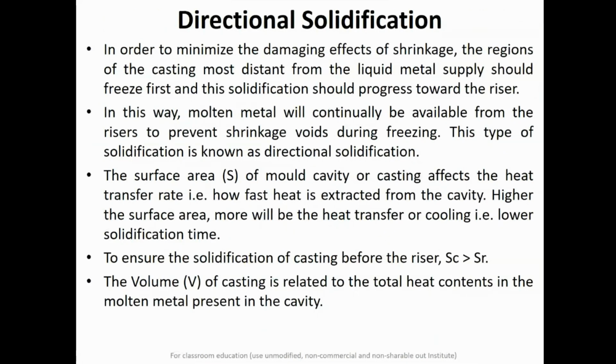Now in casting, we always take care of directional solidification. So what is directional solidification? In casting, we always aim to minimize the different types of damaging defects arising due to the shrinkage of the casting. The region of the casting which is most distant from the liquid metal supply, which means the position of the riser, should freeze first. This means your riser should freeze or solidify last, because if that is not happening, you will not have enough molten metal to compensate for the solidification shrinkage.